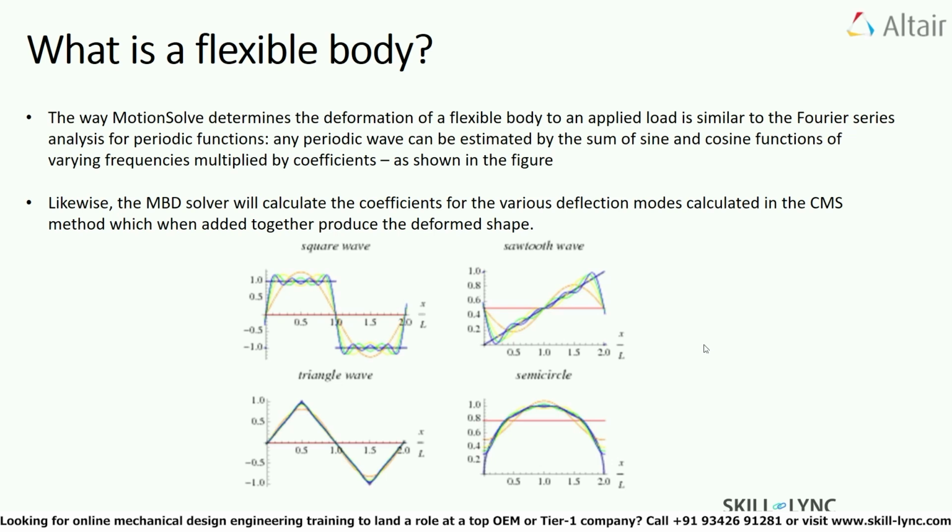In the same manner, the MBD solver will calculate the coefficients for the various deflection modes calculated in the component mode synthesis methods, which are then added together to produce the resultant deformed shape. Please make a note of this component mode synthesis method, or the CMS method. It is very important and we will discuss this in detail in the upcoming slides of the lecture.